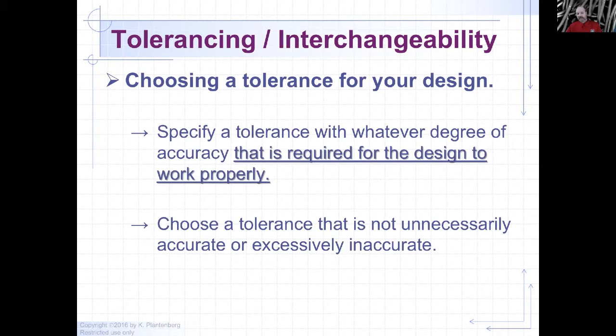So when you design things in SolidWorks, right, you can be very exacting because it's in a computer. So everything is exact, right? All your dimensions are exact. But you really want to design in some variation, right? Allowable variation, and that's where the tolerancing comes in. Okay, if you make the tolerance way too tight, then all of a sudden it's going to cost you a lot more, and it's going to be much more difficult to make.